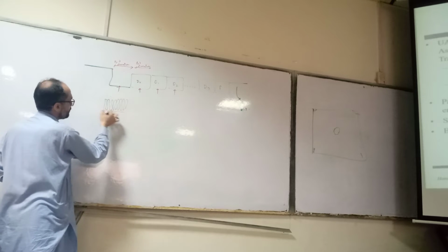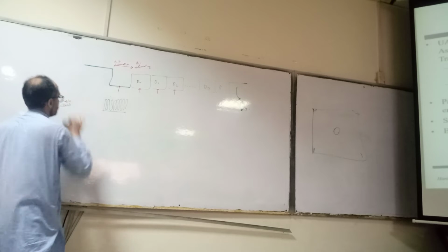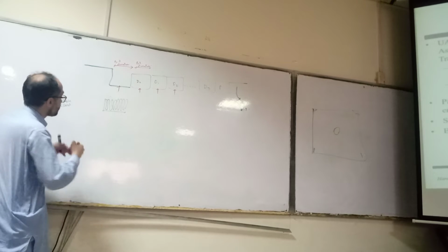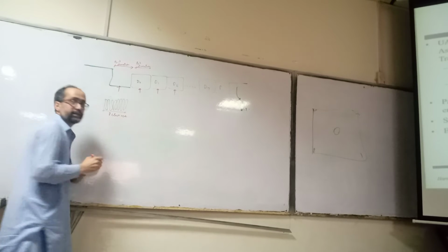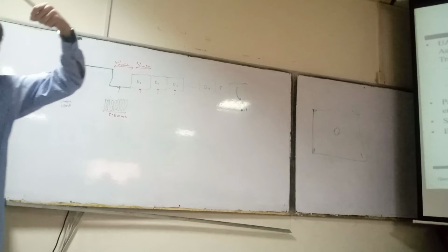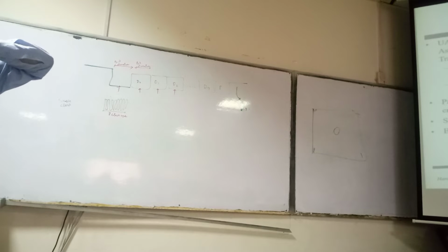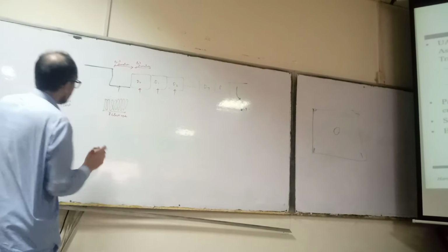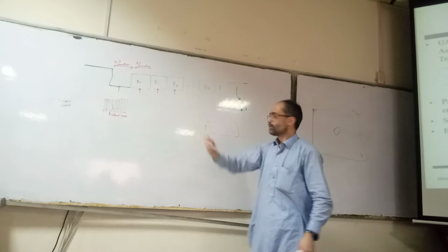And within this bit duration, we have a sample clock. Within this bit duration, there are 8 clock cycles. Now, in this case, the sampling frequency is 8 times the input frequency.